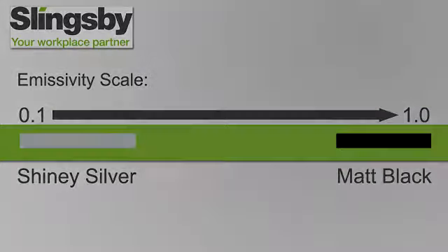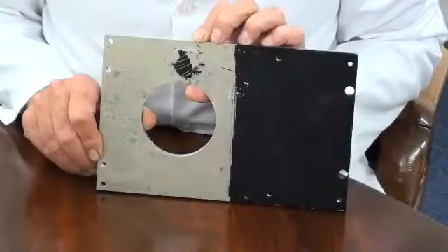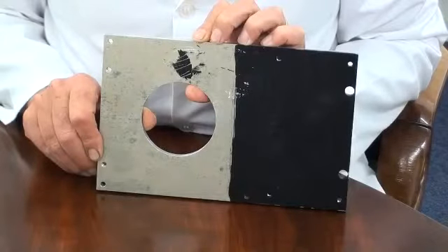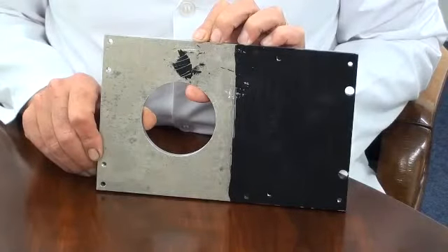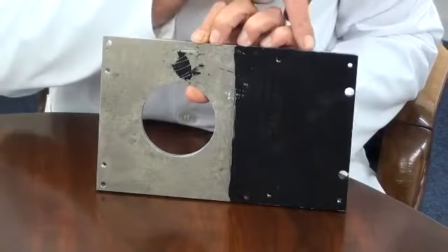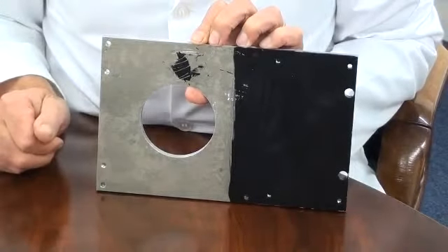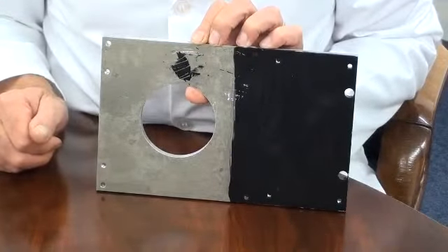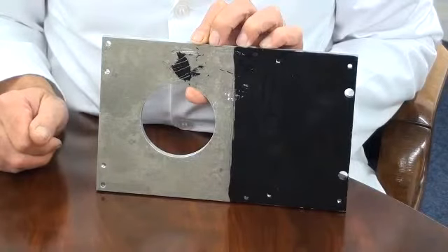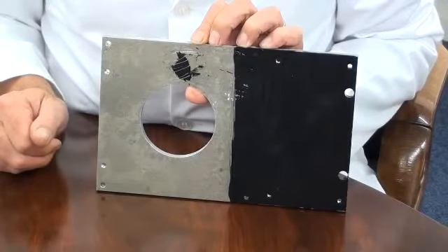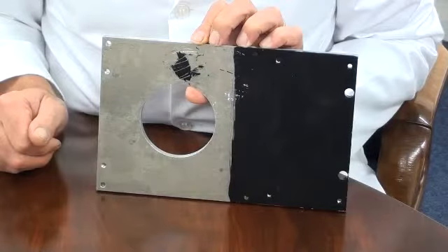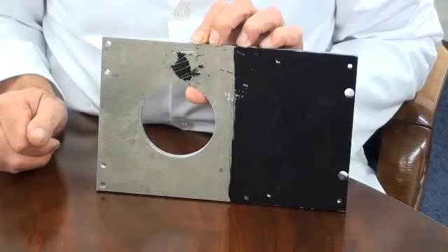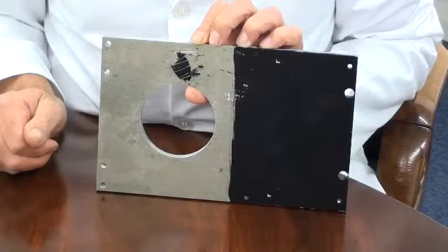based on emissivity. A simple way to overcome this is to paint a small area of the object to be measured matte black, or paint a piece of masking tape matte black and stick it to the surface of the object being measured. Black ball paint or an aerosol from a car accessory shop will do. It's not the thickness of the paint, but it has to be solid in colour.